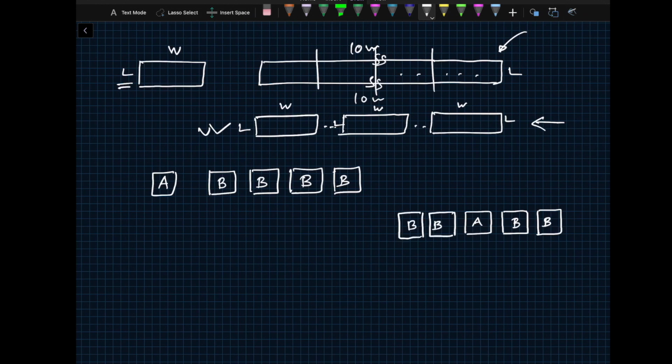So then you would get pretty good matching, because the common centroid of B transistors and A transistor is the same. And even better layout would be if you do one A transistor here, and then you would do the other transistors over here. So this would be your B, and B, and B, so that it's right in the middle, the transistor A, from which you are multiplying.